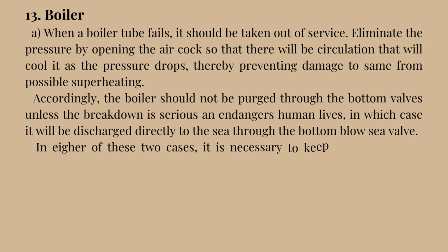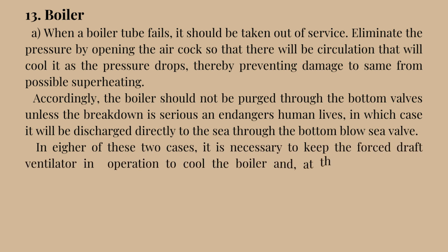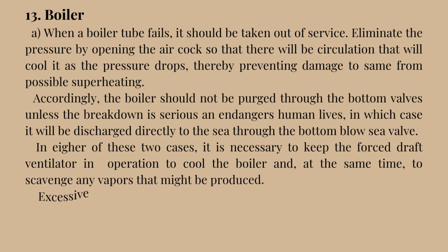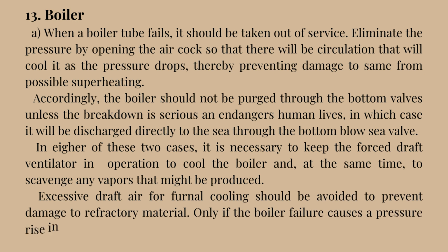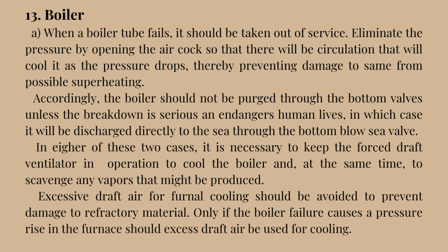In either of these two cases, it is necessary to keep the forced draft ventilator in operation to cool the boiler and, at the same time, to scavenge any vapors that might be produced. Excessive draft air for furnace cooling should be avoided to prevent damage to refractory material. Only if the boiler failure causes a pressure rise in the furnace should excess draft air be used for cooling.